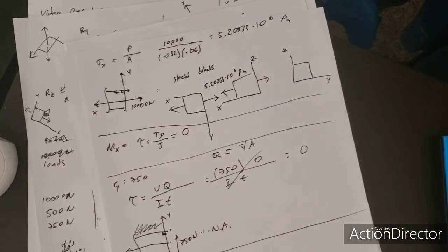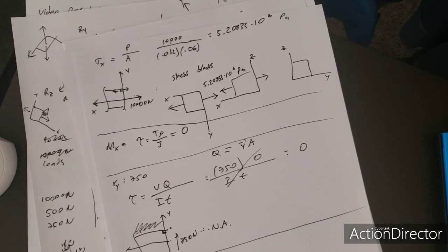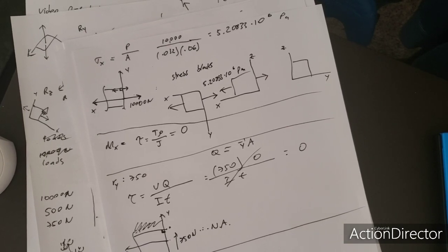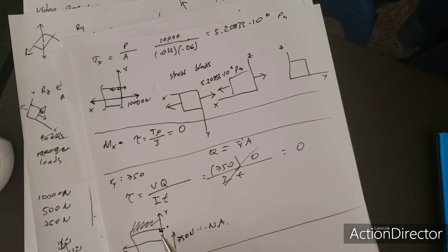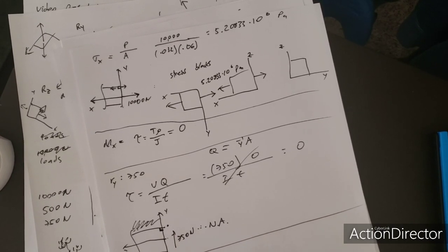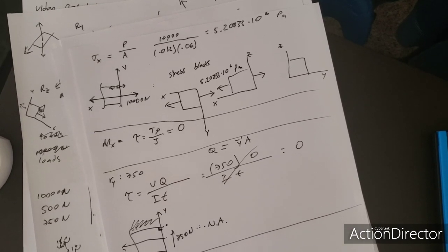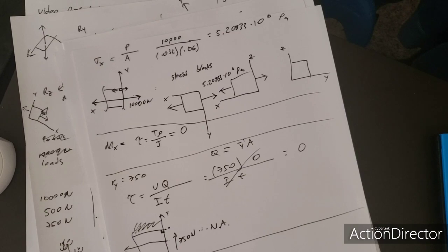Okay, and when we have a lateral direction moment, you're gonna want to look at bending moment, and that bending moment is going to create a stress on this part. So let's see, the lateral direction. For this one, you want to look down the axis the moment is acting about.